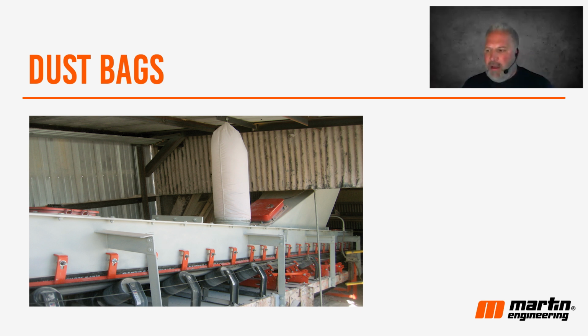So what they've done here is material is loaded onto the belt. The chute height is what it is. They didn't change the chute height, but they did cut an opening on the top of that lid, covered that opening with this vented bag, and used a curtain that you cannot see, but right here there's a slit curtain.